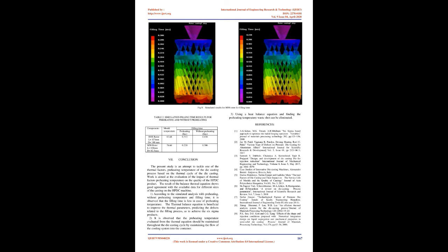Experimental validation. The above heat balance equation validation was carried out by simulation using ProCast software. The experimental setup consists of a high-pressure die casting machine of 100 T, a diesel-fired holding furnace, and a closed-loop cooling system. The die-cast rotors 100S, M50 and B48, which are used for motors, were selected for validation, with diameter varying from 50 mm to 250 mm and length from 25 mm to 300 mm.